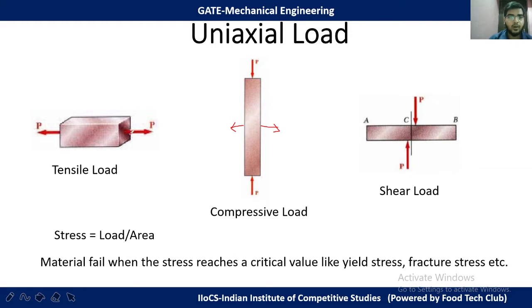Also, apart from this tensile stress, we also provide a shear stress here and also on the surface below. Then how can we interpret what will be the stress which should be considered to find the critical value of the failure stress?